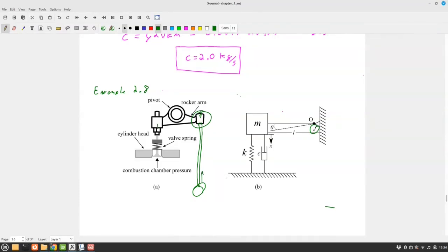By pushing the push rod up, you would push the valve down. This is your valve. It would seat against your engine chamber, and then you'd have a spring, some valve seats, valve stems, and seals, and whatnot. This is how you can move air in and out of your valve, and so this controls the valve on an internal combustion engine, like it's in your car.